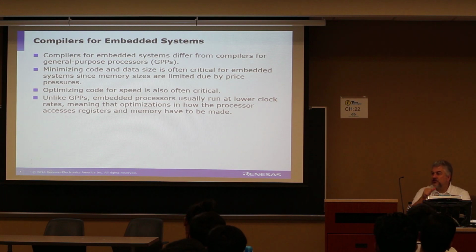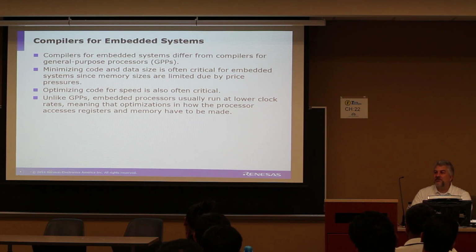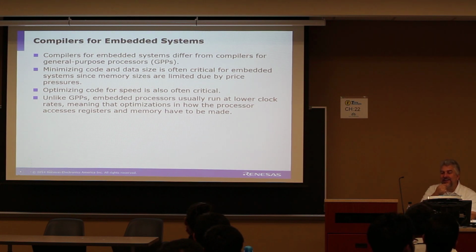What is the processor clock speed for our Renesas? That's the 12 megahertz is the input clock for the crystal into the board. But what does the actual clock run at? We have it all over the place. 100 megahertz. All right, it's the capability of the processor itself taking that input clock signal and actually multiplying it, and basically getting a faster clock out of that 12 megahertz.